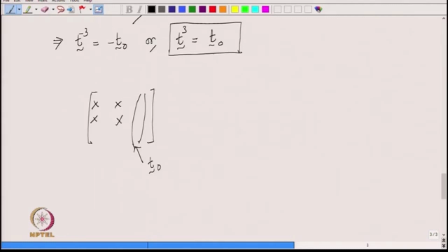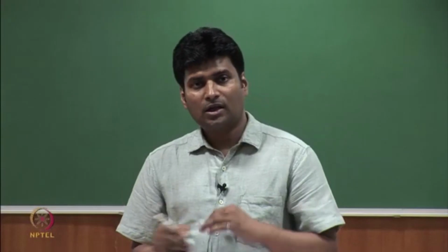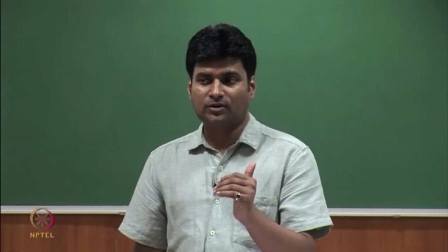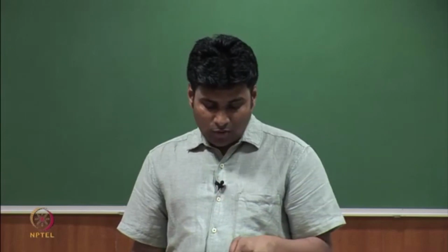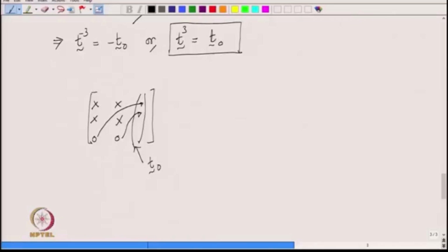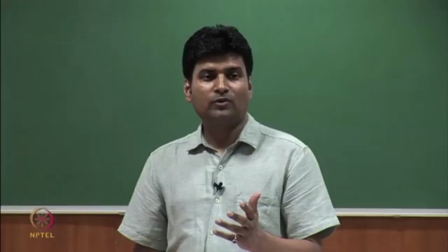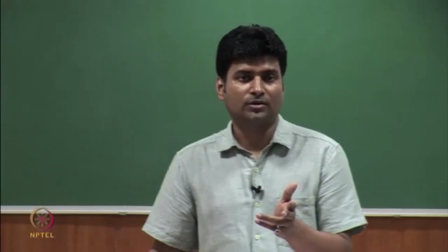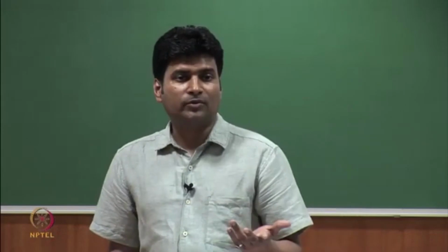But the third component of the first and second column will get known because of the symmetry of the stress matrix. So, this one and this one, they are the same as what is here and what is here. This is all you can say about the stress matrix at points which are close to the surface. So, you know about 5 entries here, but 4 of the entries are unknown, which you can find by solving the stress equilibrium equation, but the remaining you can guess right away.